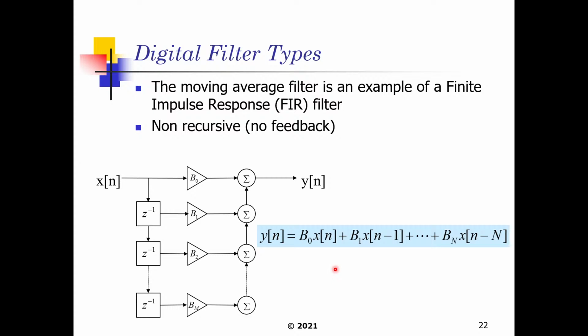This feed-forward system filter design is also referred to as a finite impulse response filter, or FIR filter. The reason why it's feed-forward is, if you watch the nature of the equation, everything was just adding and everything was in terms of x on the right-hand side. So there was no feedback of the output, being y of n here.